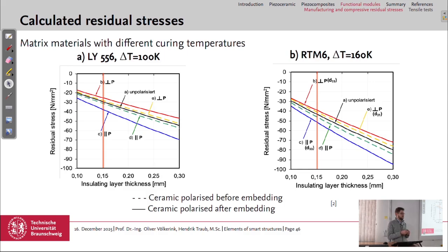And therefore the brittle ceramic, which would fail under tension earlier than under compression, can be stressed higher under tension, and this leads to a more ductile behavior. This enables that we can bend the actuators to a curved surface where the ceramic without the polymer and without the stresses would just break.